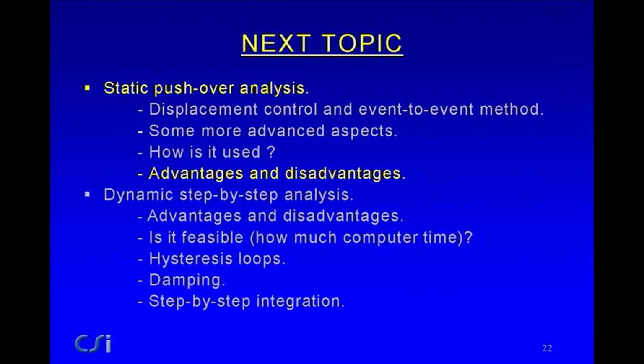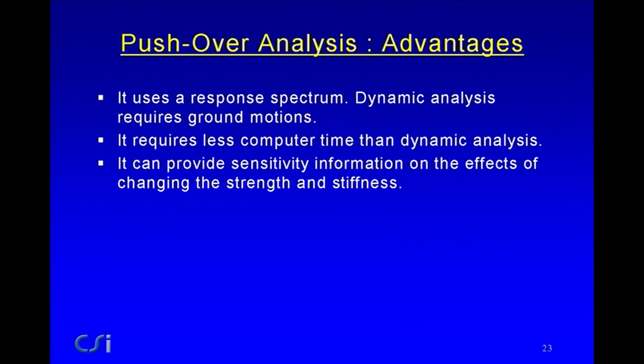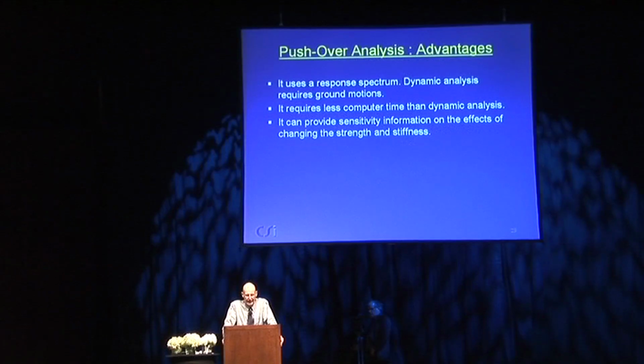So the next topic is what are the advantages and disadvantages of static pushover analysis? Advantages: it uses a response spectrum, whereas dynamic analysis requires ground motions. That, from a design point of view, is a major advantage. It requires less computer time than dynamic analysis, possibly a lot less computer time. And it can provide some sensitivity information on the effects of changing strength and stiffness.